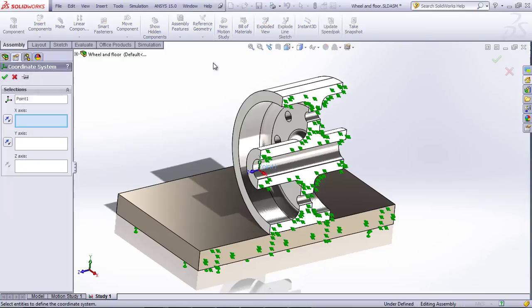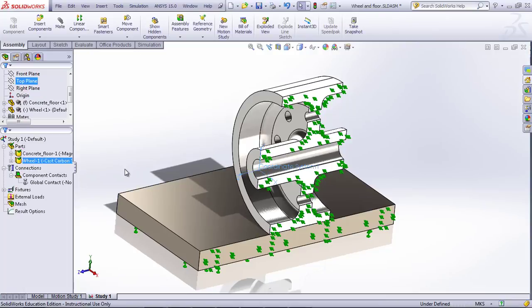So go to the coordinate system now. The x-axis, well, we got 0.1. That's the big thing we want. The x-axis, the z-axis, we're okay with what we have. We basically want the z-axis. We want it to be aligned with the axis of our hole. So if it's aligned already, we don't have to do anything else. We can just green check. It's okay where it's at. All right, so that coordinate system is already active.